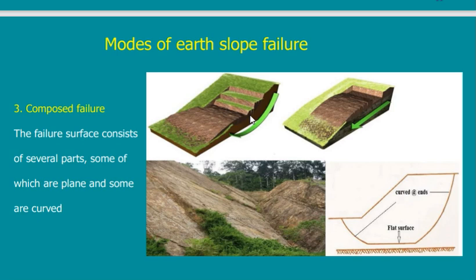I cannot solve it, because I do not have an equation or a program or a method for solving any shape in the world. I have to approximate it to known shapes so that I can study. So suppose I give you something like this, and you don't have a method to study this, then you can assume, okay, I will assume that this is a toe failure, a base failure, and I will draw a curved line from here up till this point, and I will study these cases.